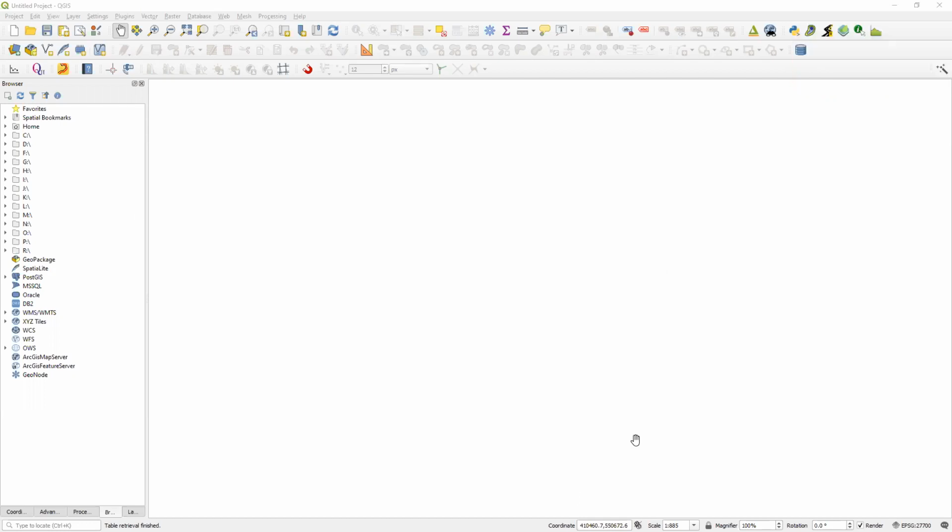What I've got is I've got the right tile, which is part of the steelworks, but it's just repeated numerous times. It hasn't actually imported the whole country. So, right. If your tiles are repeating, what you've done is, when you add the XYZ tile URL, you've put it in with just the numbers in. You haven't substituted the numbers for the Z, X, and Y. Right. It looks very pretty, I must say.